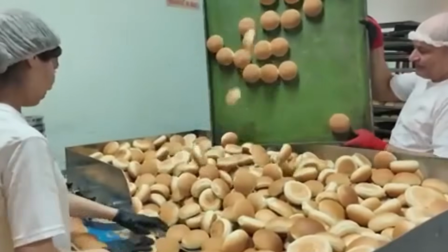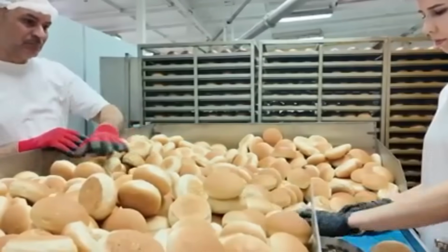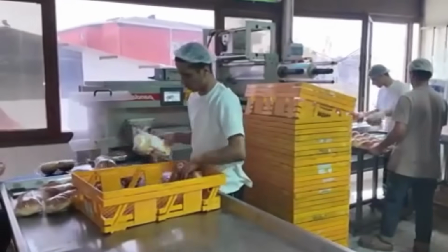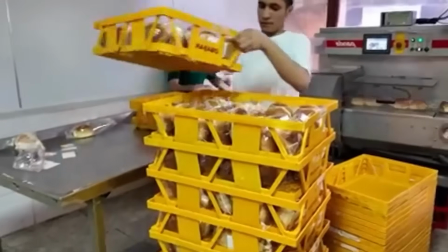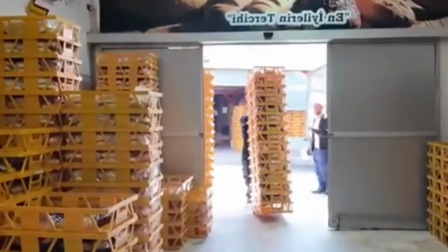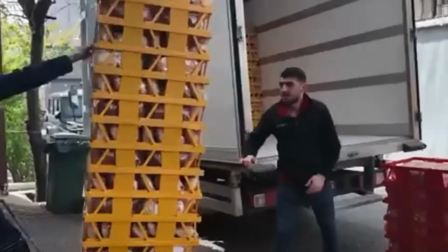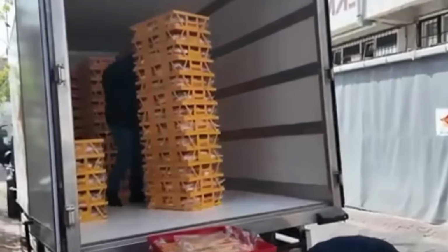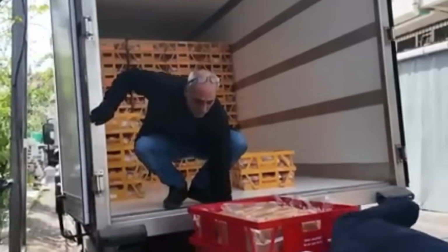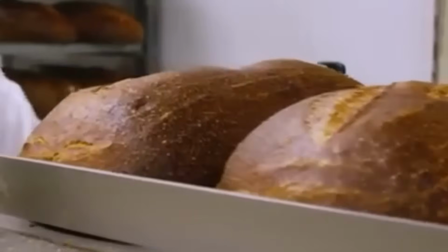Robotic arms pick up loaves in sets and stack them into shipping boxes, which are then sealed, labeled, and passed to the palletizer. The palletizing system uses multi-axis robotic arms to stack cartons onto wooden pallets in precise formations designed to prevent shifting or damage in transport. Slip sheets are placed between layers for stability. Once full, the pallet enters a stretch wrapper, where plastic film binds the load tight from base to top. A printed label is applied to the outer edge of the film, detailing product information, origin, destination, and tracking codes.